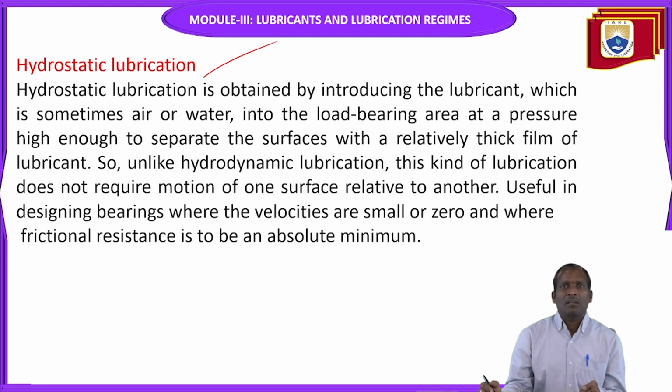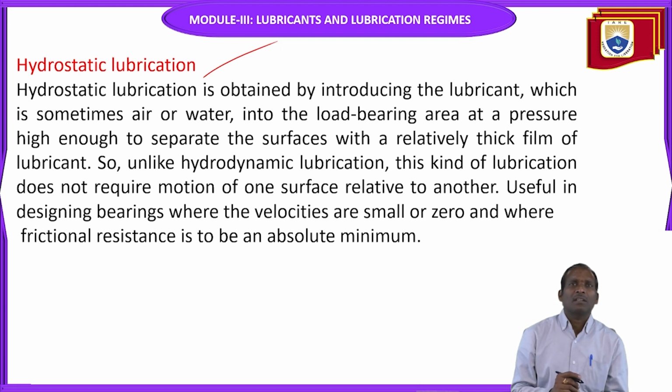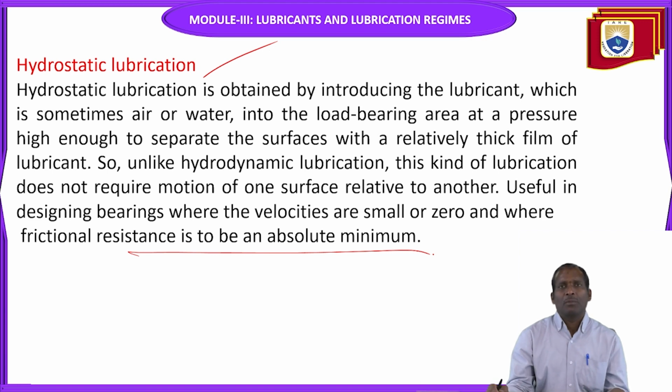Unlike hydrodynamic lubrication, this kind of lubrication does not require motion of one surface relative to another. It is useful in designing bearings where the velocities are small or zero and where frictional resistance is to be an absolute minimum.